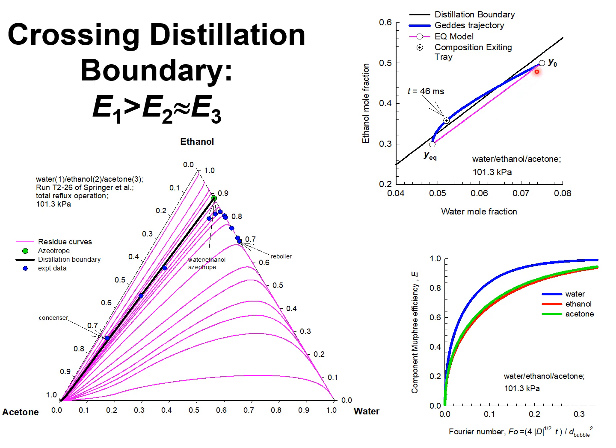In other words, the Maxwell-Stefan model anticipates a scenic route to equilibration, and since the equilibration is stopped before thermodynamic equilibrium can be achieved, we have the phenomena of boundary crossing.